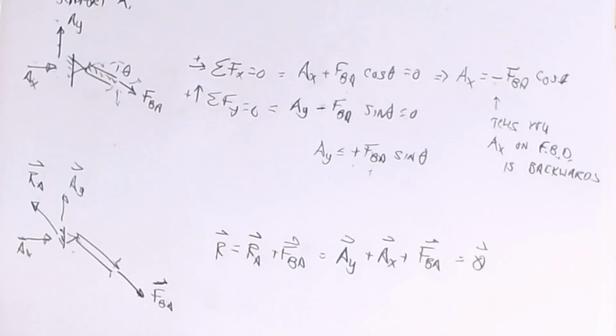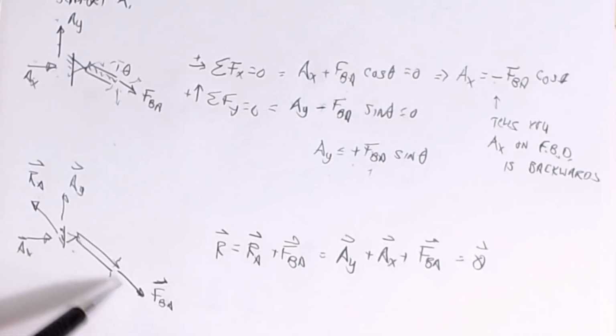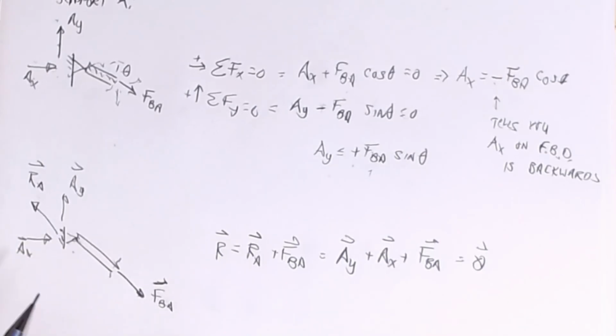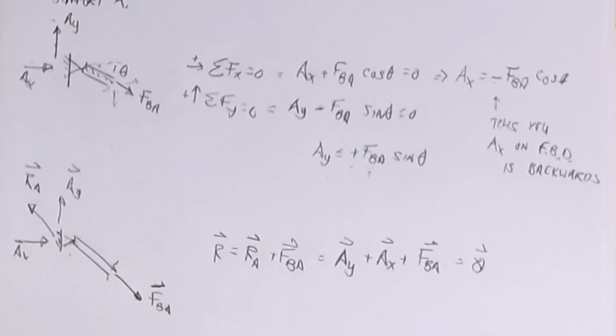Now, there is also moment equilibrium where the resultant moment must also be 0, but I'm not going to worry about this because all the forces are acting through the same point, that support on this one. But we'll pick that one up here in the coming videos. So I hope that's made sense to you. Remember, it's always wise to draw a free body diagram. I thank one of my former students for coming up with that acronym, but it works. So W.I.S.E: weight, internal, supports, and external, as we start to work on that.